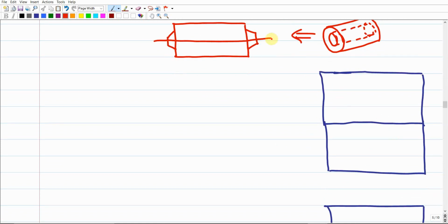So if we draw this cylinder that is going to be cast horizontally in the mold, it is represented in this way. Half of it will be located in the cope and the second half of the cylinder will be located in the drag, and these are the core prints of the core. This is how the pattern is located inside the mold. You could consider that this is the mold here. I can even give some colors here. This is the mold cavity.